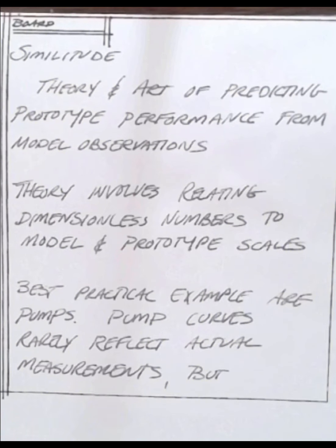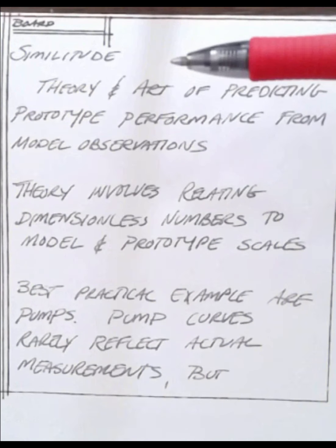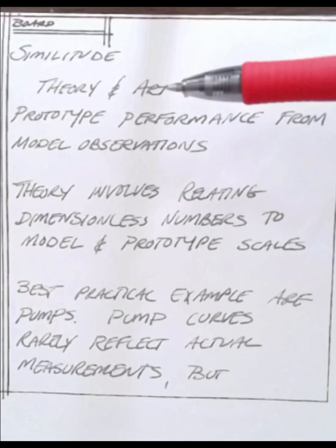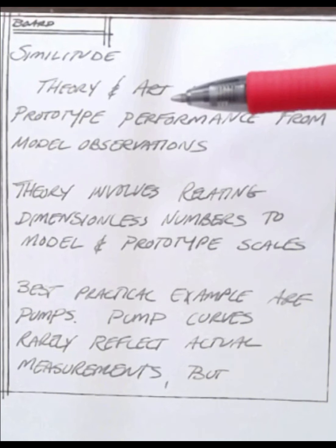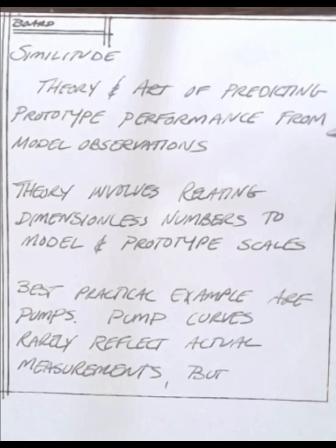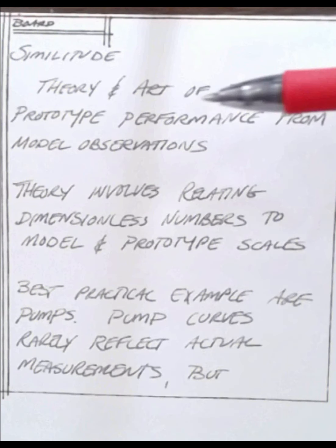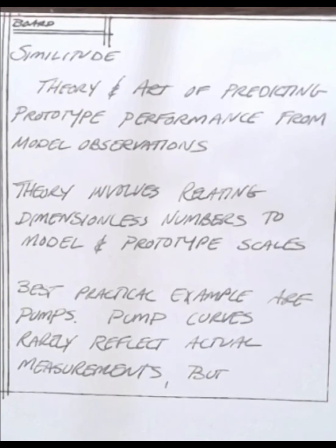And the subject of this lesson, or this part of the lesson, is similitude or similarity modeling. So, in many fluid mechanics studies, or many real engineering studies, we construct small models of our full-scale operation to examine the behavior on those small models, and we use similarity relationships to scale up the responses of those small models to full scale. And so similitude is the theory and art of predicting prototype performance from model observations.